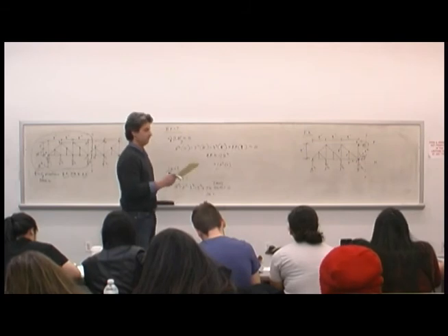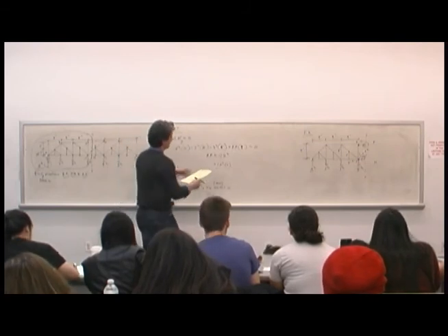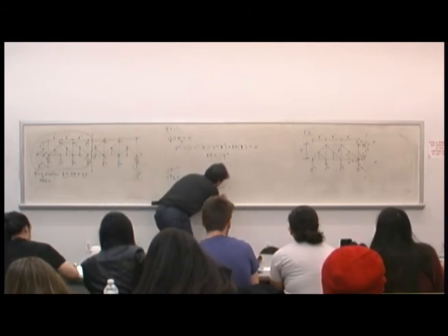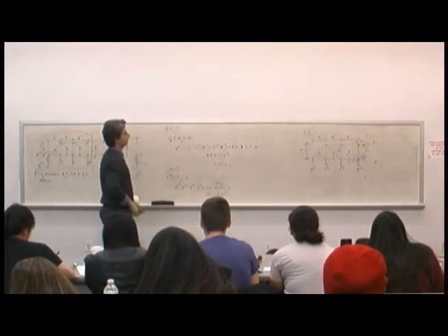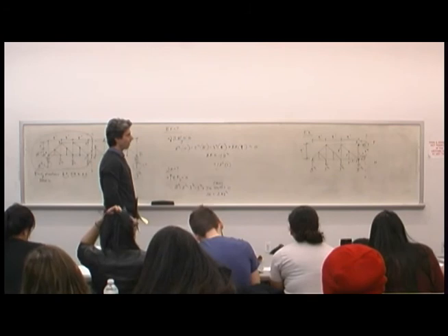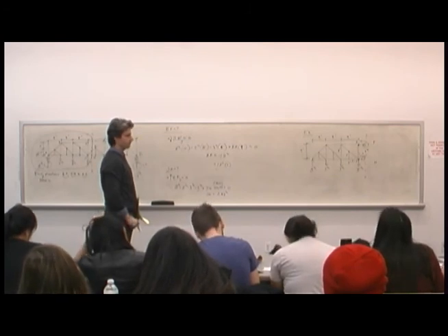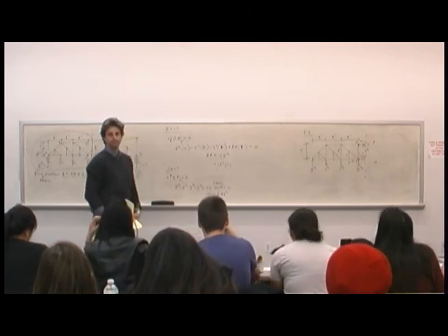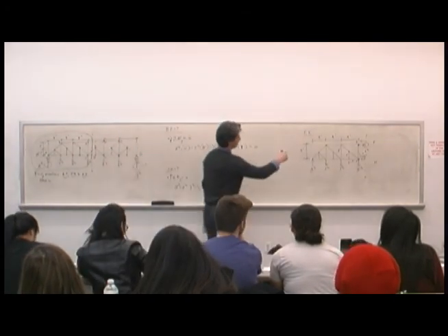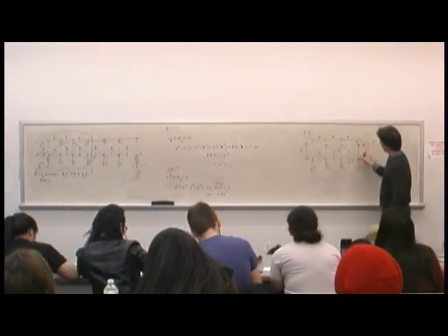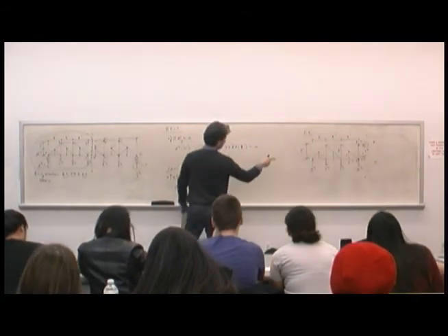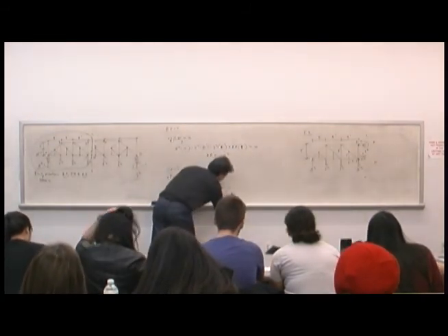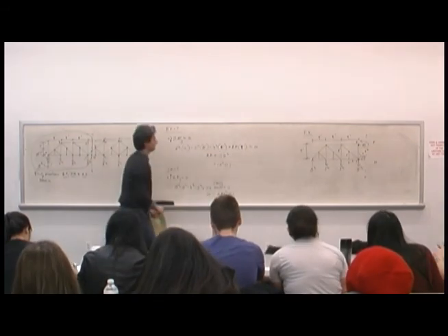2.83 is what I got. And compression or tension? Tension, right? It's pulling away from this node. This is the direction of the force we drew, so it's pulling away, so it's in tension. It's a positive number, so that direction stays, and it goes into tension. So JK is in tension.